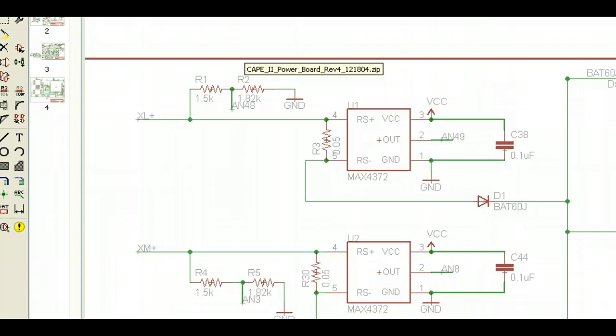There's basically 4 main parts to this thing. The inputs are the solar panels, and there's 14 of them, so there's 14 identical circuits. And then there's batteries, so there's 3 batteries, so there'll be 3 identical circuits. There's some switches that switch the solar panels onto the main bus and the batteries onto the main bus. And we have a watchdog timer and some analogs. So if you just look at this thing a piece at a time, we'll try to make it simpler for you.